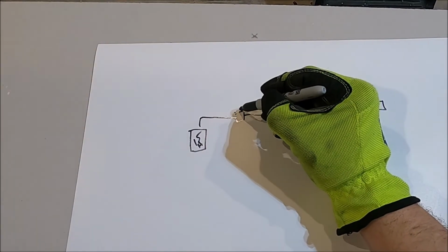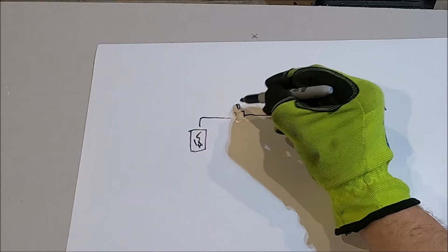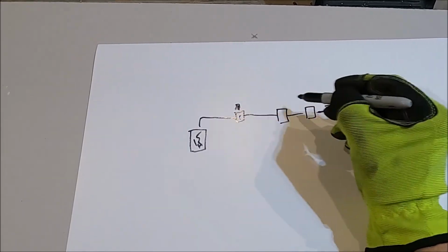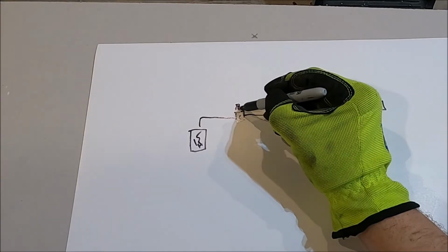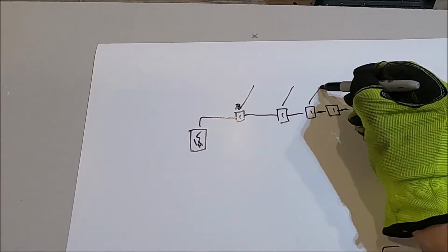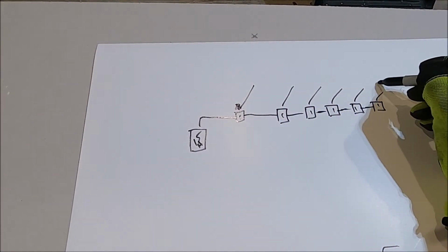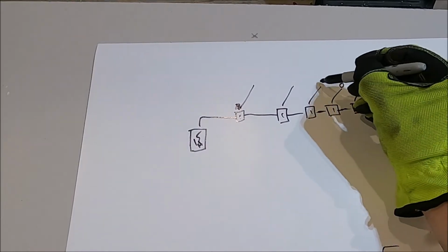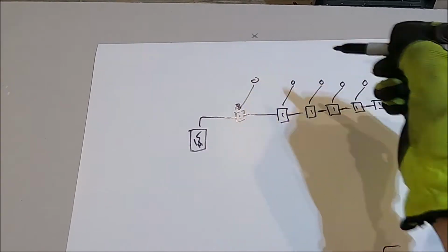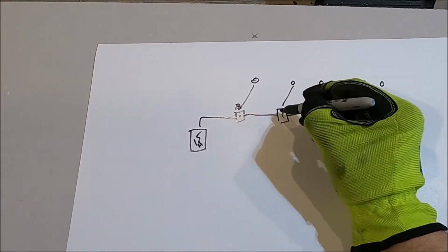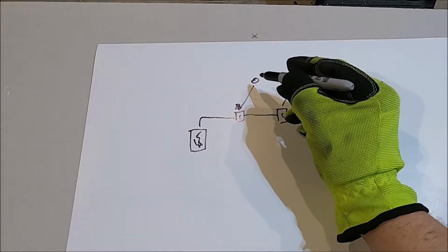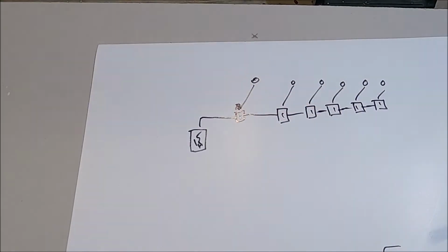And then all you're doing with your switch, actually let's just make a switch out of each one of these, so let's just say this is your switch, is you're creating a branch circuit to go up to each one of the lights. It's your switch that's controlling the hot feed that goes up to the light to make it power on.